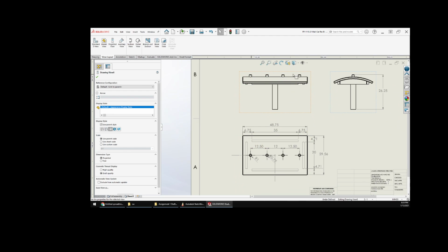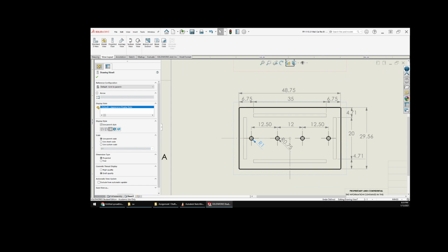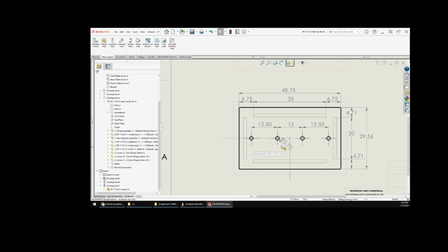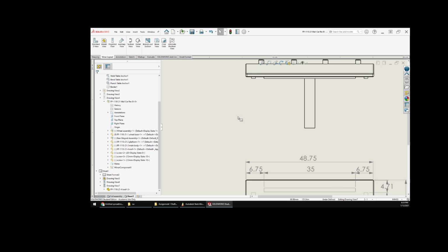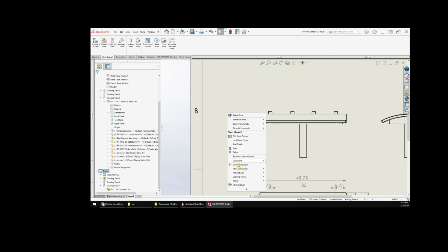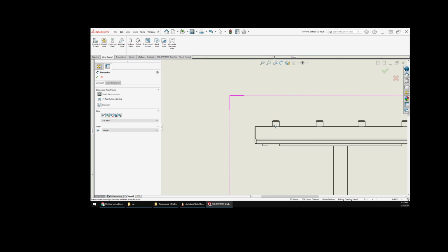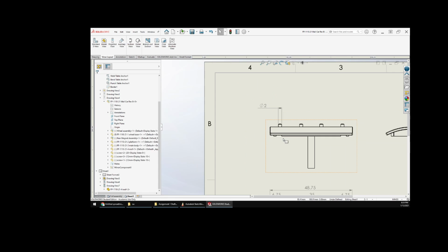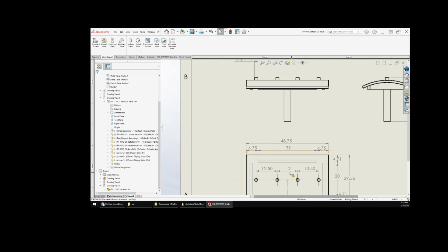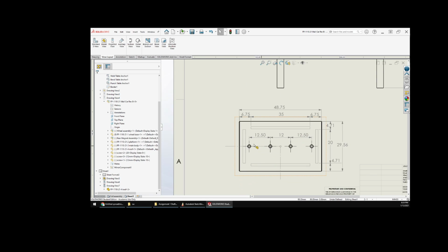So now up on this part, what are my dimensions? I don't need to dimension these because they're all there. I don't need to dimension the diameters. But now, let's say this was too clunky in here. Well, it may have been better for me to come up here and dimension it this way. You know, what works better? I like it down here because that way all the dimensions to these are the same. Oops, I also wanted to dimension...